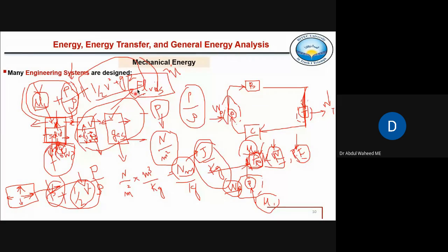इसीलिए आप fluid mechanics में study करते हैं pumps और hydraulic turbines. मैं hydraulic turbine कह रहा हूँ, steam turbine या gas turbine नहीं कह रहा. ठीक है, because in case of steam turbine और gas turbine temperature also changes. ये जिस तरह यहाँ जो हमारे पास case है, that is a steam turbine. Steam enters at a higher temperature, when it leaves इसकी pressure energy भी change हो रही है, इसकी internal energy भी change हो रही है. जब आप steam में से energy extract करते हैं तो उसका temperature भी drop करता है, लेकिन आप liquid में से energy extract करें तो उसका temperature drop नहीं करता. ये आपने pump के case में भी देखा और hydraulic turbine के case में भी यही होता है.